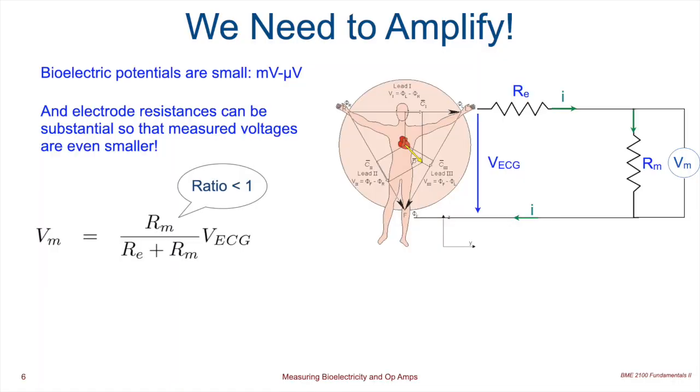These are very small signals, and it's hard to convey, transfer, or transmit these signals without some noise being introduced, and that noise distorts the signals and may even wash the signals away so we can't even see the useful information. So we need to do something first before we actually use the output of this simple measurement circuit. And of course what we need to do is amplify the signal, right? Should have seen that coming.